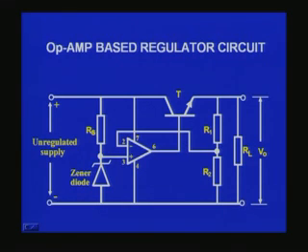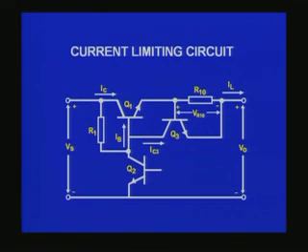Okay. Before I go into that, I want to just mention to you that you would always have a situation where the value of the load will be reduced to such a low value that you will be drawing a very large current, which may sometimes cause damage. For example, if inadvertently I connect a wire between the output terminals, it corresponds to short circuiting the power supply. When you short circuit the power supply, you are almost connecting zero resistance across the terminals. This will correspond to a very large current flowing through the regulator. This might spoil the devices inside.